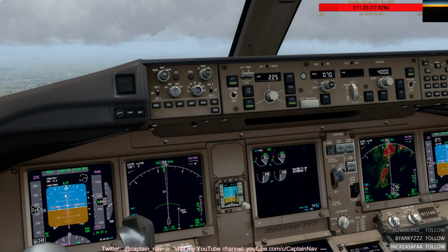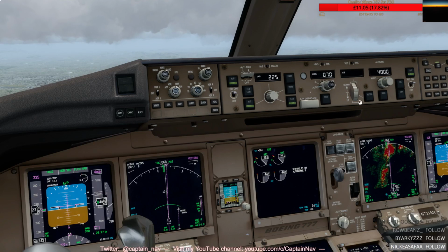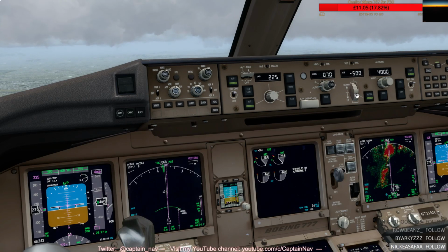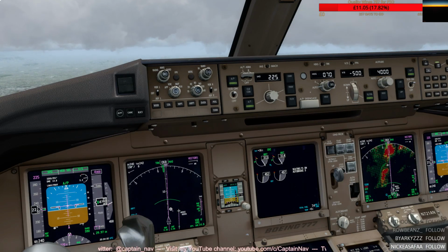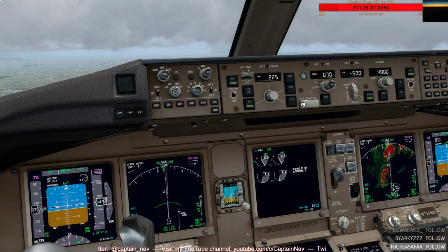Once you get to the commanded speed, the automatics lower the nose again. Now I can take vertical speed again, because otherwise I'm gonna be a little bit low. So vertical speed and flight level change help a little bit to get more control over the descent.